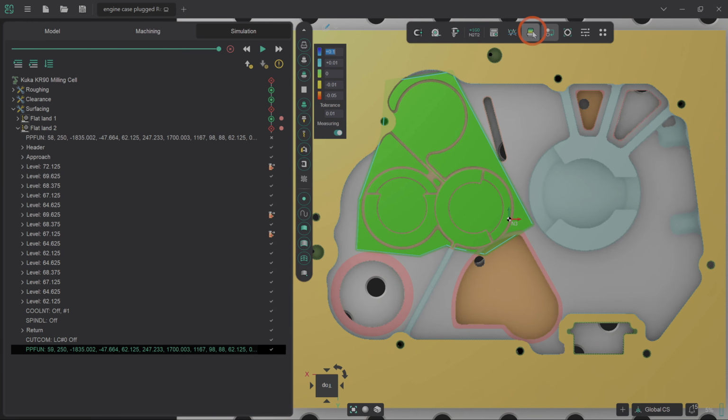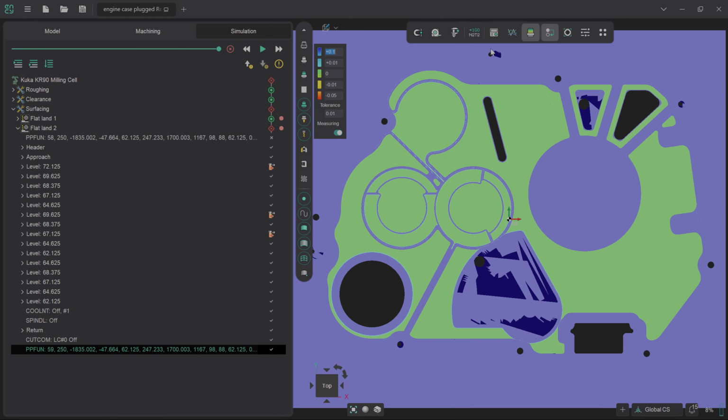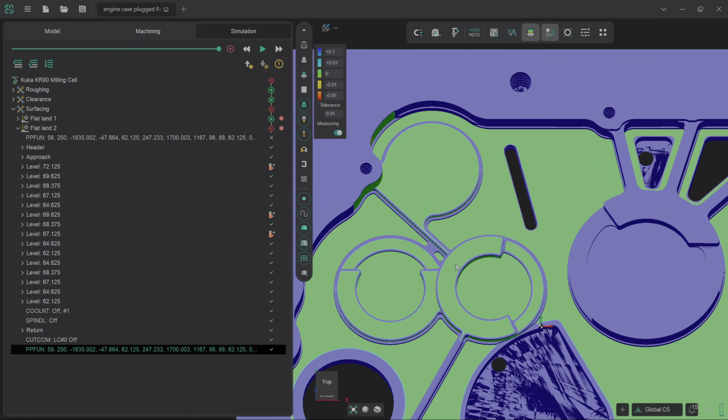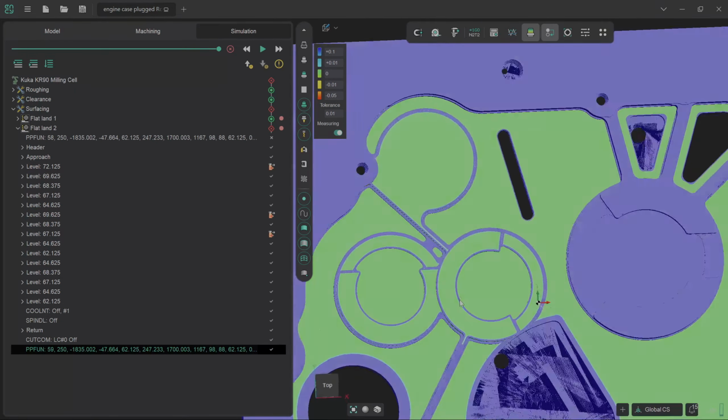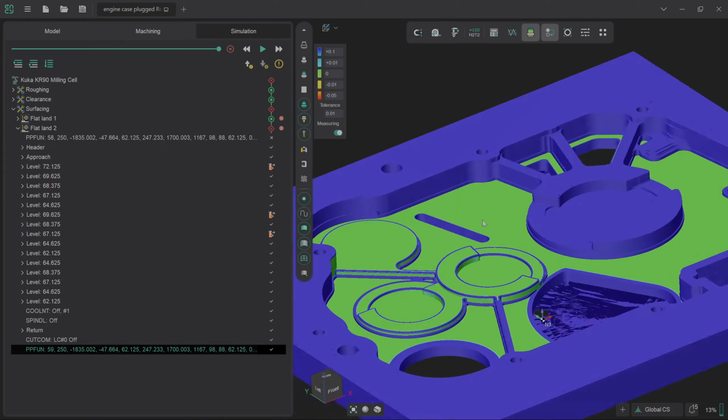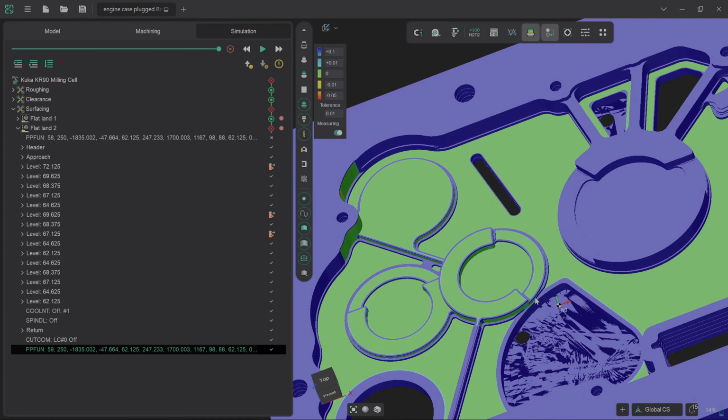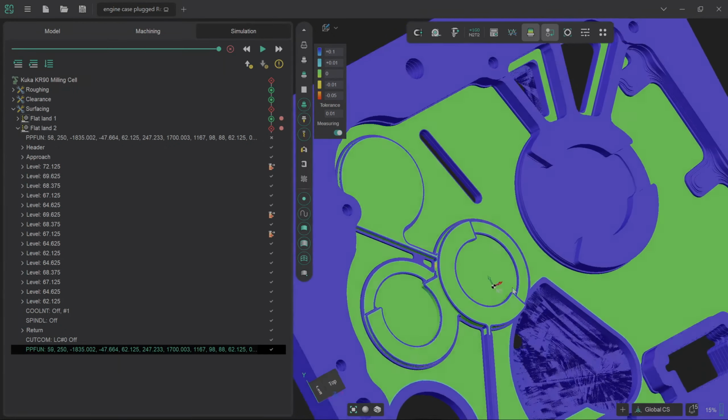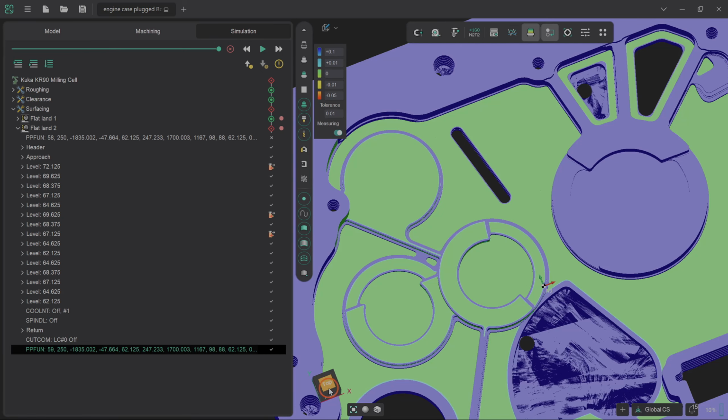We'll set the verify compare, and we'll see that this region's coming up perfectly clean compared to what we need. So I'm not sure where the gouge complaint is coming from, but I'm not seeing any that are notable. There's a couple of very, very small nicks, but only in very tiny regions.